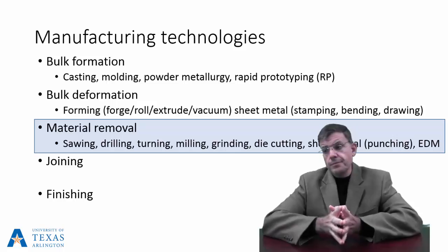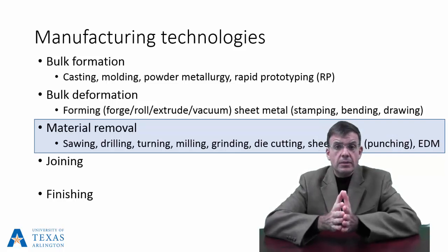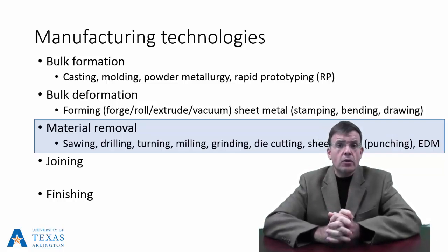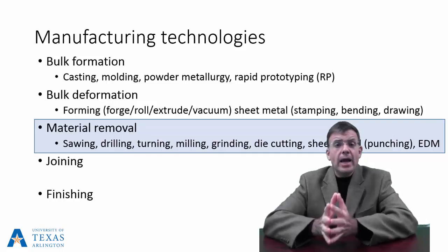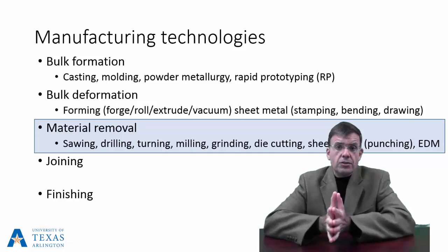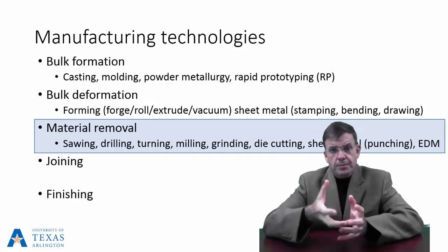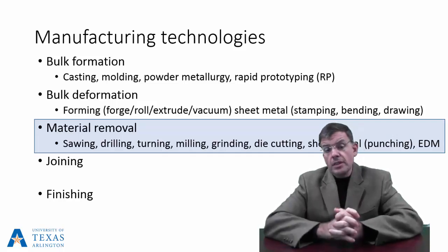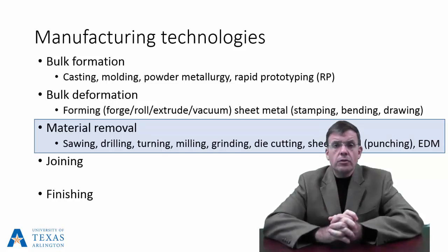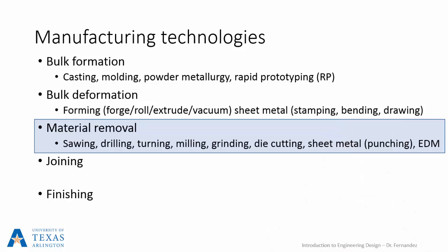Now, when we drill, we can also ream. That's another process that slightly enlarges a pre-drilled hole in order to get a high accuracy final hole. We can also associate the concept of tapping here with drilling. A tap will be used sometimes in conjunction with the drilling machine in order to create an inside thread by means of the tapping process.